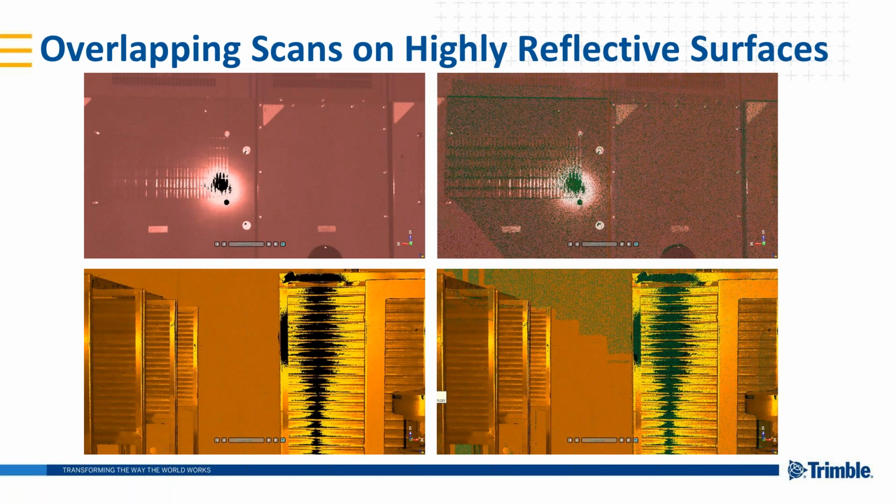When scanning areas like these stainless steel enclosures, it is common to have a blown out area in the point cloud when the laser scans directly perpendicular to the reflective surface and the return signal is too strong. And here are a couple of examples where an overlapping scan from another position filled in areas that were not captured from the first scan.